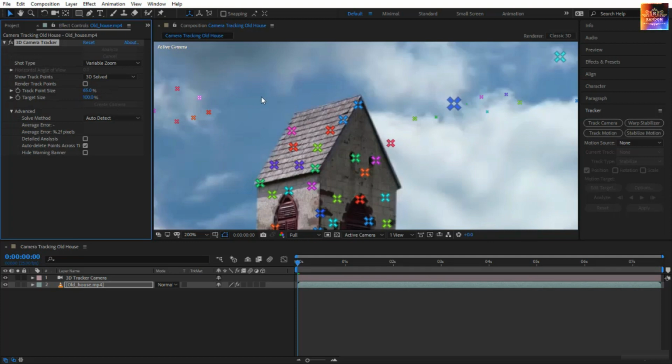There is the target here. This is this circle. Notice, I'll make it a bit smaller. Let's see how the target operates. If you point, for example, in between 3 track points, just like this, it has selected 3 track points. And then, using these 3 track points, you can define a plane in X, Y, Z in 3D. You notice the 2 track points on the right are further towards the camera than the one on the left, this one over here. It's proposing to you that you can create a plane using the 3 track points.